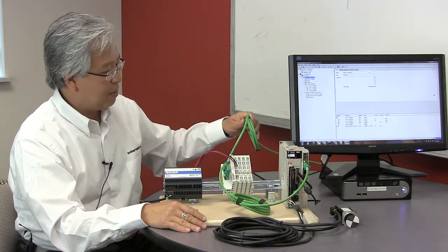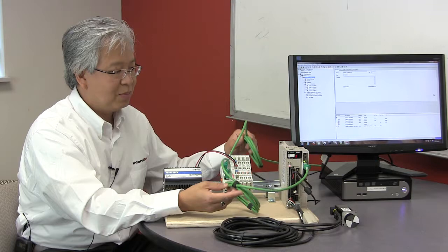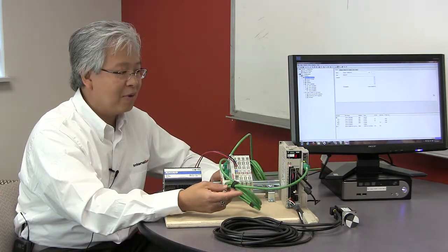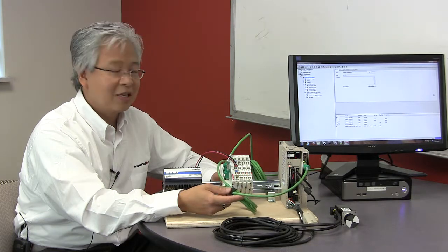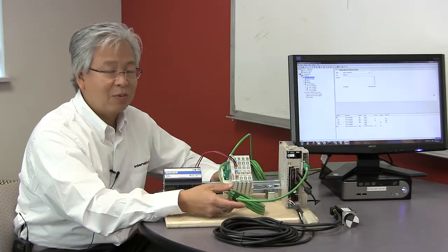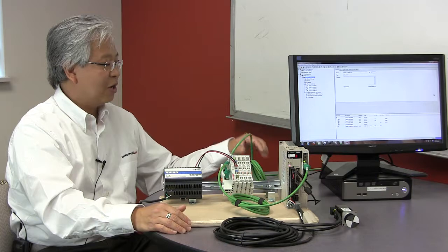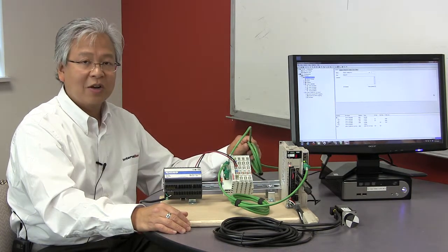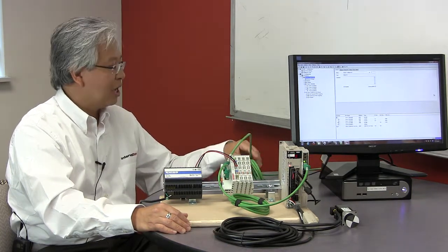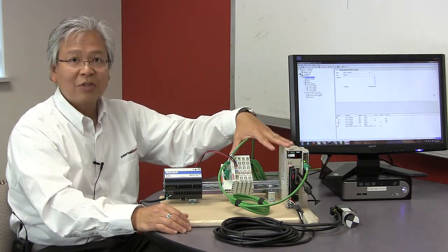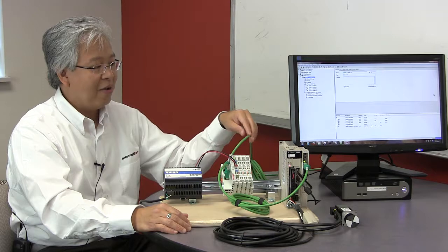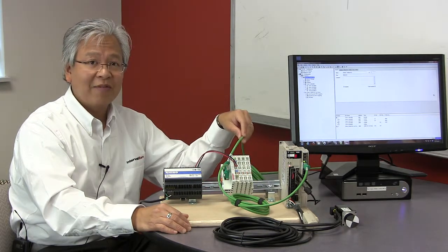One of the big benefits, not only with EtherCAT, is being able to use standard Cat5, but one thing you should know is that safety is integrated into this bus. Not only is this a fantastic real-time communications bus, but it's also a dedicated safety bus, because there are dedicated channels to pass the safety messages from your controller all the way down to your motors and slaves. So everything is integrated on a single Cat5 cable.